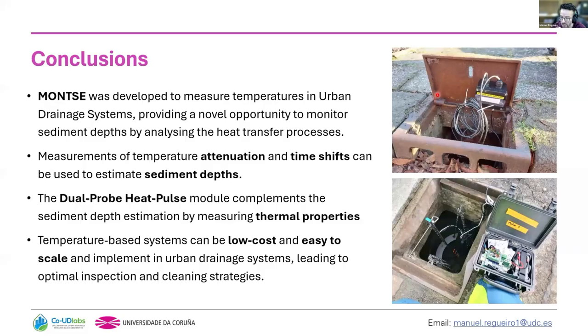And for example, currently we came up with a solution that we found is the better way to install it, at least in Zurich, with gully pots with a big volume: to install this system so it is easily removable. So you basically have to unscrew this one and then take out, like in a pole, all the sensors with the box with all the electronics, and then you can perform the cleaning.